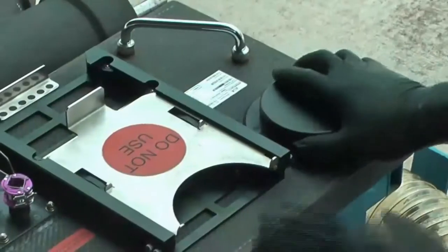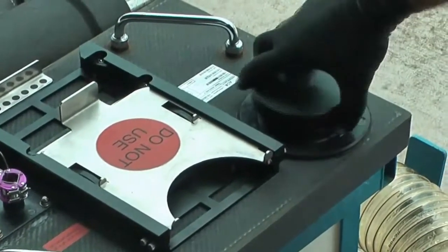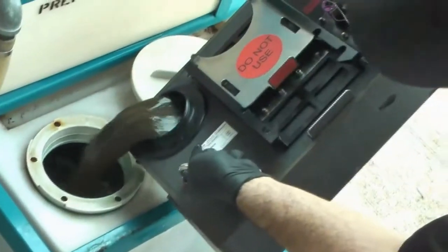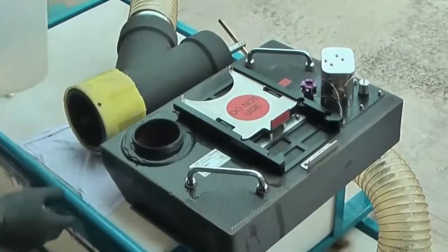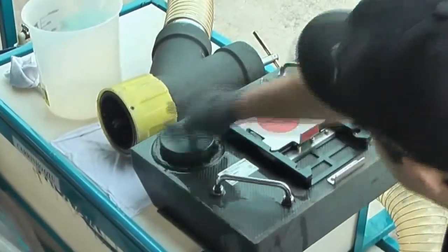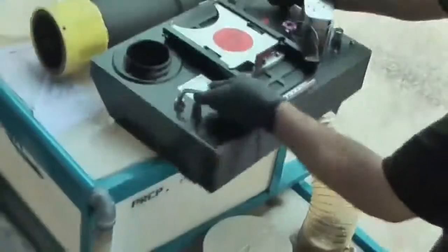Pull the waste tank by the waste tank handle and remove it from the airplane. Open the cap and empty the waste tank into a disposal facility. Clean and rinse the waste tank, for example, close the cap, fill the tank with 5 liters of water, shake, pivot it, and finally empty the tank again into a disposal facility.